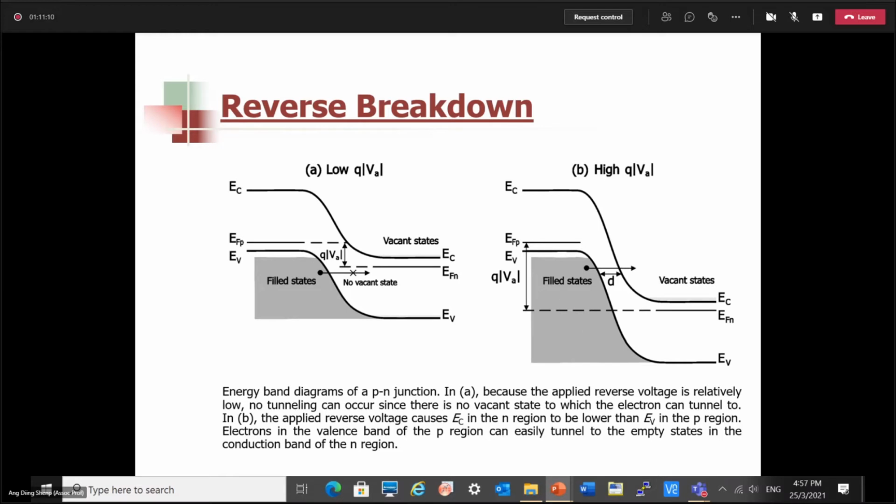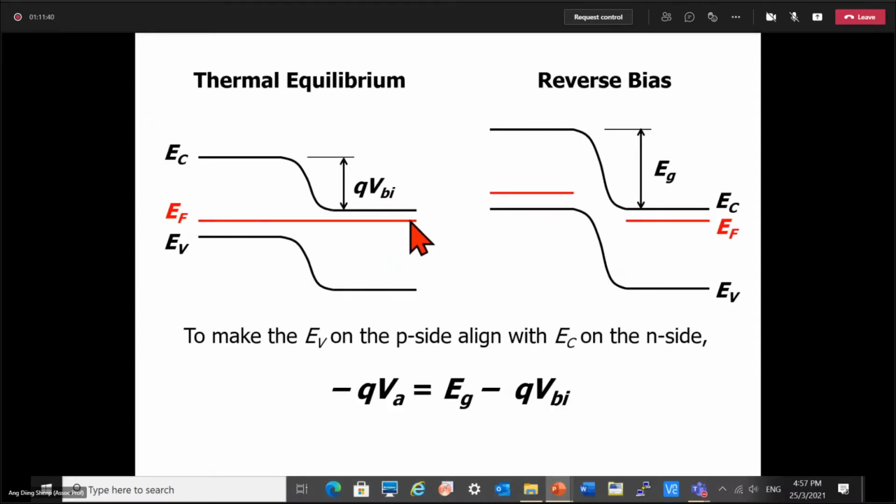All right, because the moment you apply external voltage to the PN junction, the PN junction goes into non-equilibrium. So in non-equilibrium, the Fermi levels do not align as there is charge transfer across the junction. The Fermi levels are only aligned under thermal equilibrium. While it is not shown here, this is still not under thermal equilibrium. In fact, I think I have a diagram just now. Right, so under thermal equilibrium, the Fermi levels on both sides are aligned, because there is no net transfer of charge across the junction under thermal equilibrium. Okay. Yeah, thank you.